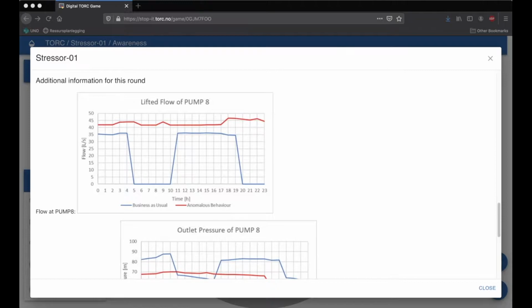where. So you can look at the pressure meters, because we have several pressure meters in the network, and he finds out that at the outlet of pump 8, we have a very big drop of pressure. So you can see in the picture the outlet pressure of pump 8, a very high pressure drop. So, in comparison with the other sensors, he is able to recognize that the leak must be close to the outlet of the pumping station. So basically the leak is almost localized, and the utility finds out that the stressor was